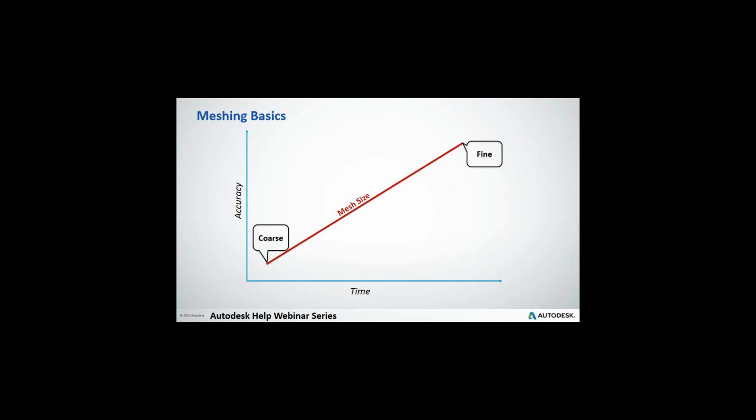And then you figure out that you have some flow regions or temperature profiles that follow the mesh scheme or the mesh elements, where you say, okay, here I need to further refine my mesh because probably I'm not capturing well the gradients in this region. So then as you go to final analysis and you need to match experimental results, you would need to refine the mesh and have tighter mesh elements to capture high gradients, as we mentioned.